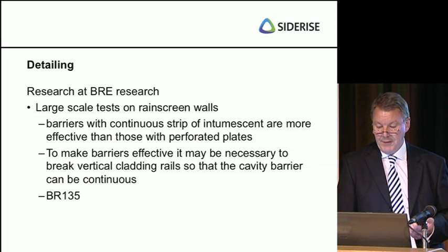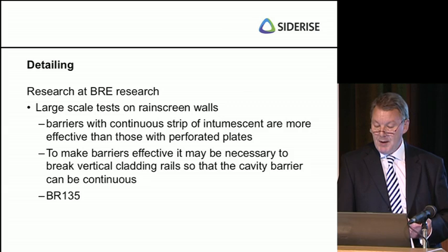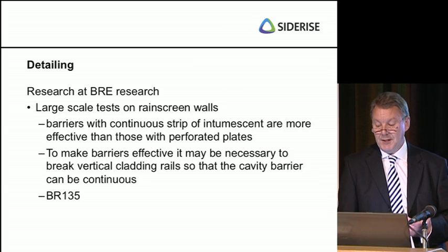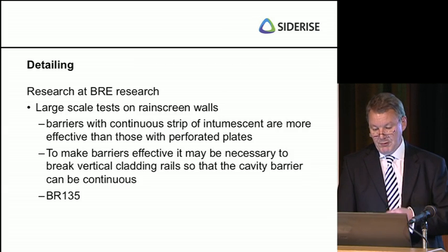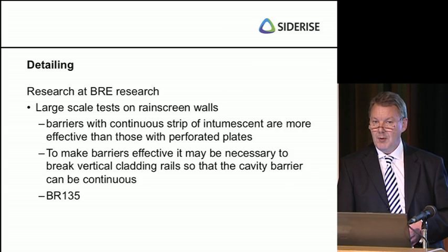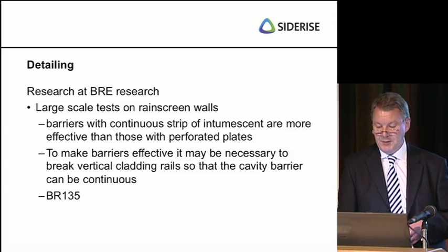The research also found that to make barriers effective, it may be necessary to break the vertical cladding rails so that the cavity barrier can be continuous. The research is shown in the BR135 document as posted previously.